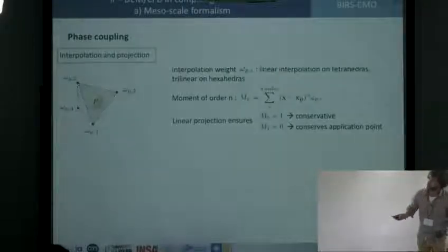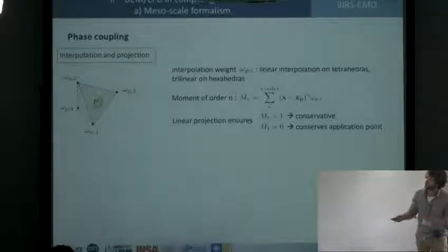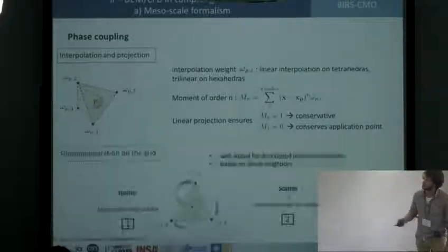Regarding interpolation and projection steps, which are often needed in this type of simulation, we use the same weights for both operations, which come directly from linear interpolation, which possesses interesting moment conservation properties.